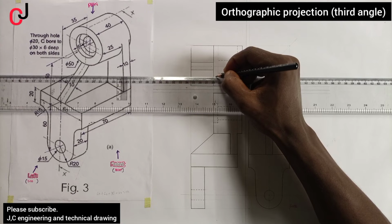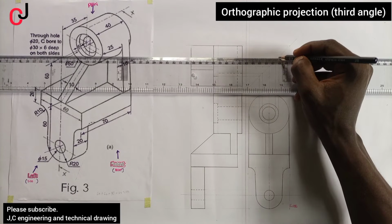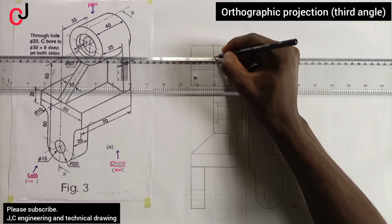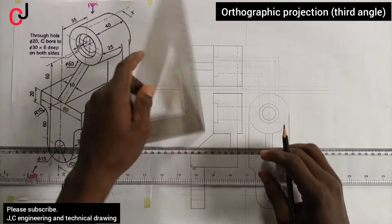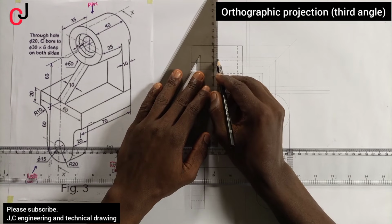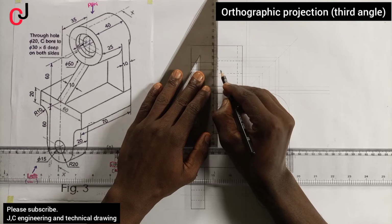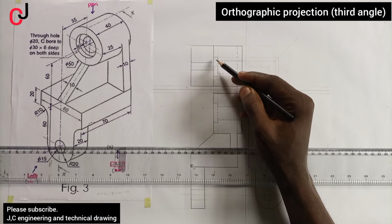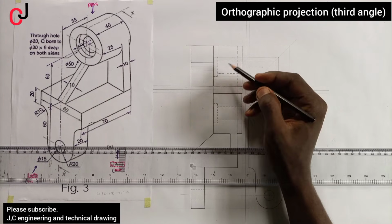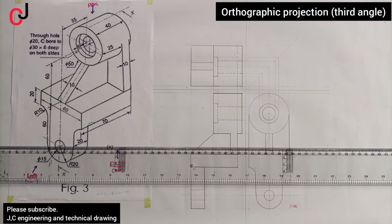It's not a true line, so it's only 6 mm deep, which is this. Also you do similar stuff here, project, and then you indicate this with a broken line. Also you do similar stuff here, indicating that the 30 diameter only went 6 mm deep, while the 20 diameter went all through the hole.